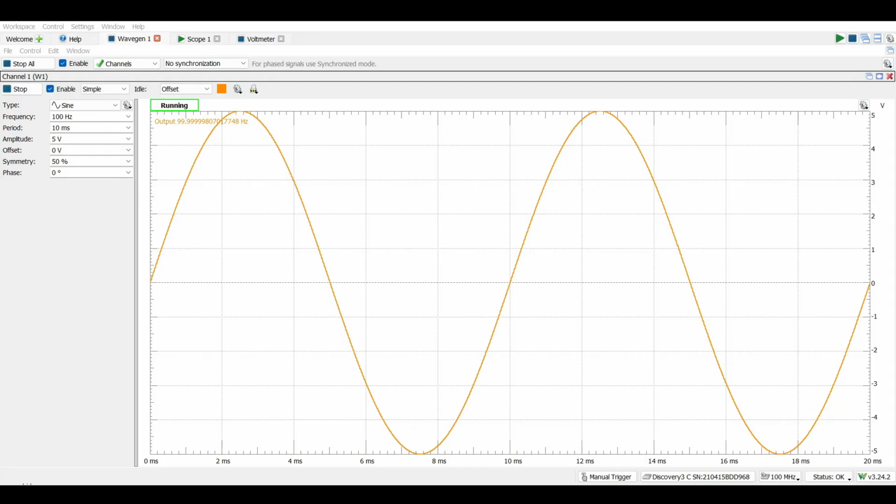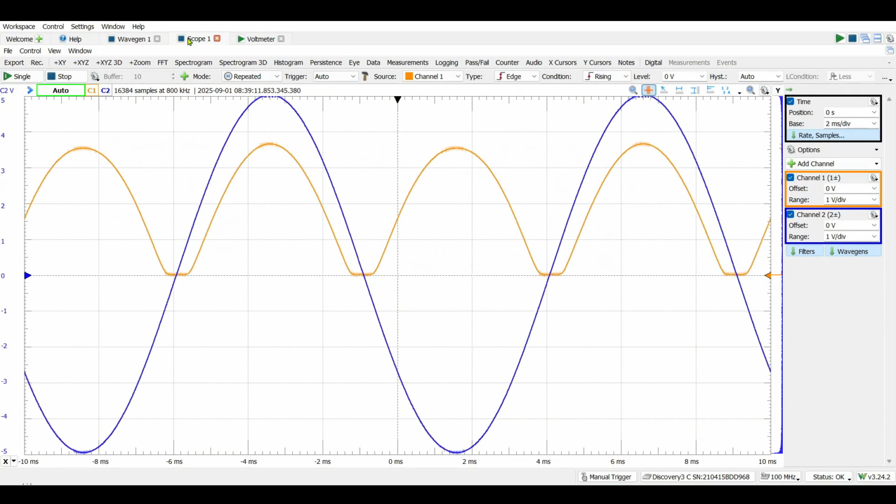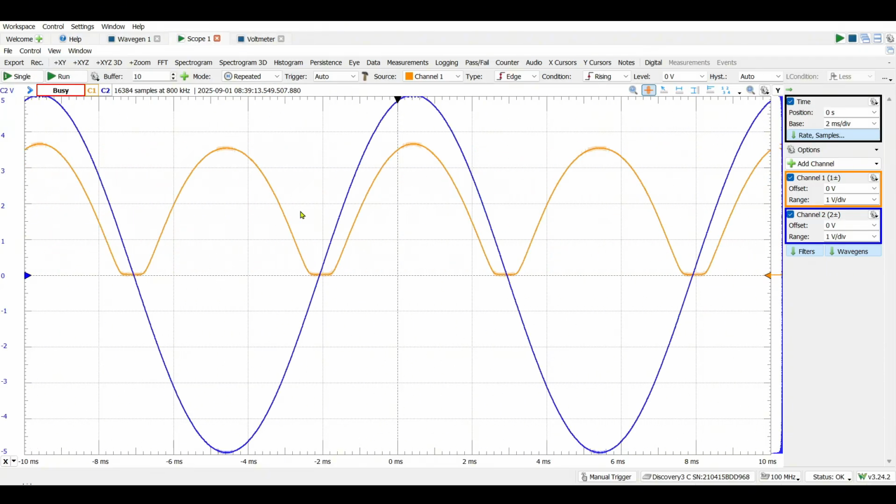Moving into our waveform, our created voltage in our wave gen is 100 hertz at 5 volts peak. After it started, if we go into our scope, we're creating a similar voltage to the Multisim. We have our 0.7 volt valleys from the forward biasing cost of the diodes, and then a pulsating DC voltage that is a frequency twice that of the input frequency.